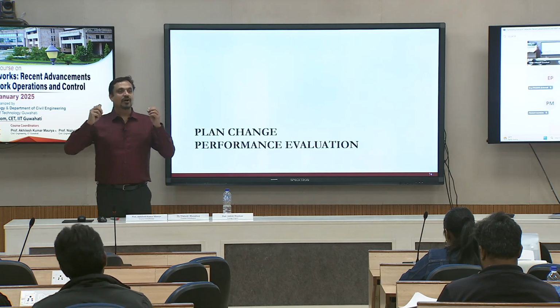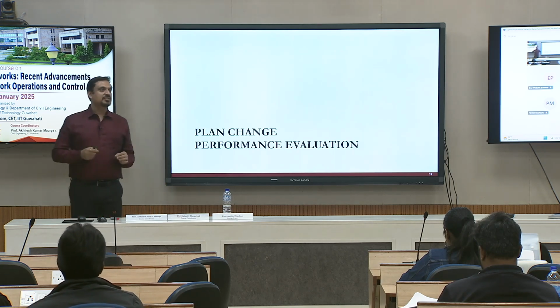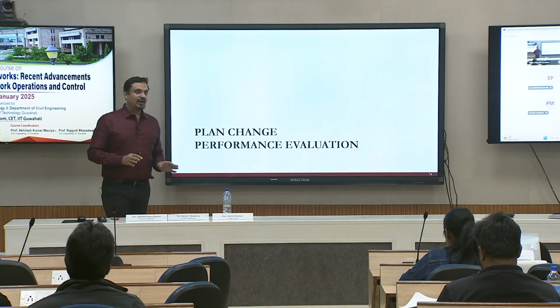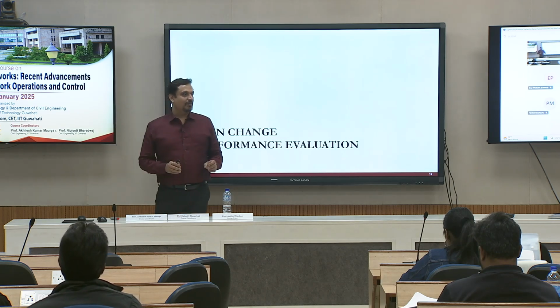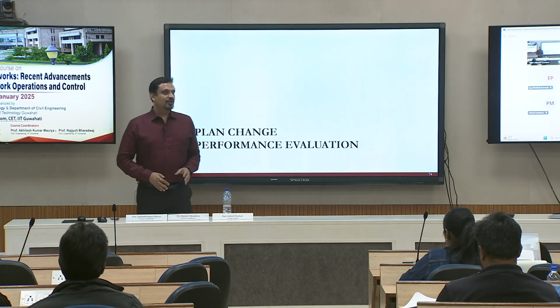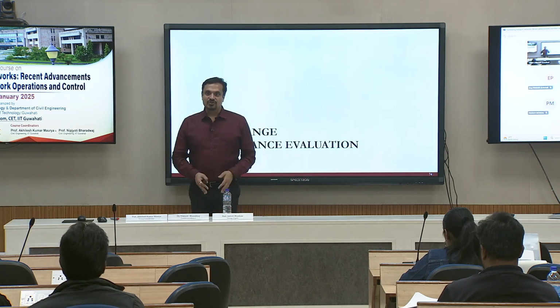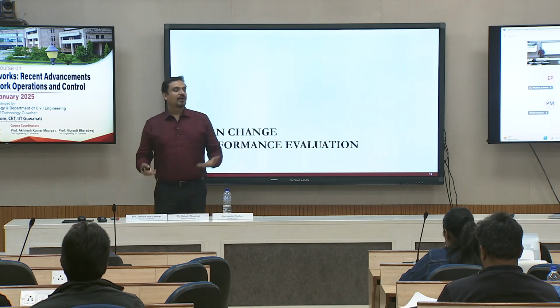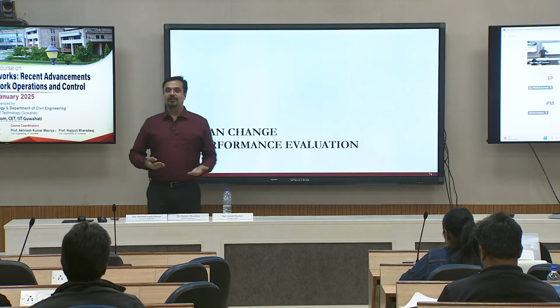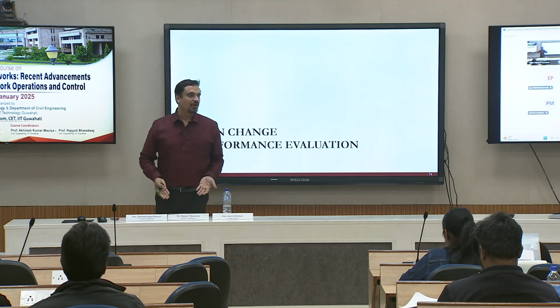I've given sufficient all red time. I've given sufficient yellow time. So that I've not changed. I've only changed the single parameter, cycle time and the green time. So I did an observation last Thursday. I did my change today. I got a new observation. I see the value. Yes, 4.5, 3.5. The delay has gone down.